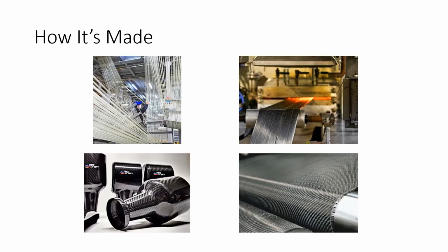They then are going to travel through an oxidation oven that is roughly 400 degrees Fahrenheit, which allows them to pick up oxygen molecules. This allows the fiber to have a high melting temperature of roughly 365 degrees Celsius. As the fibers are oxidizing, they change color to turn black, which will prime them for carbonization. Next, furnaces will heat the fiber in an oxygen-free gas chamber. This will help expel the non-carbon atoms and will transform the carbon atoms into bonded crystals. This process gives the material its high strength ability.